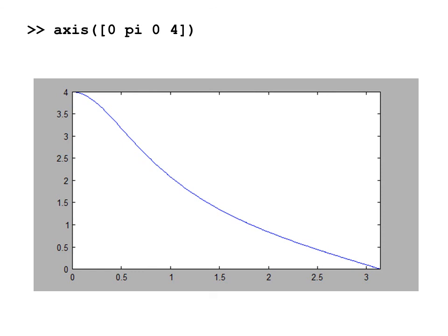But the important thing is I zoomed in on the positive frequencies omega 0 to pi. Now we're plotting frequency response of this digital filter, as is commonly done, over the positive frequencies only. And 3.14 is the highest frequency displayed, 0 is the minimum frequency displayed, and we're seeing a characteristic low-pass filter response.